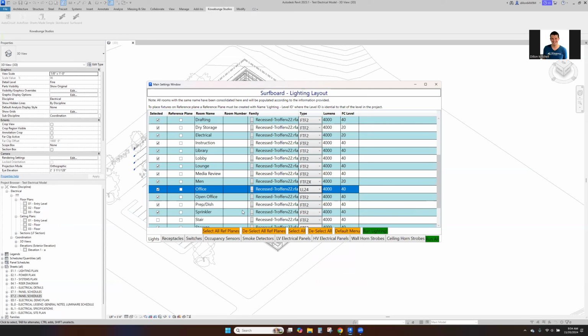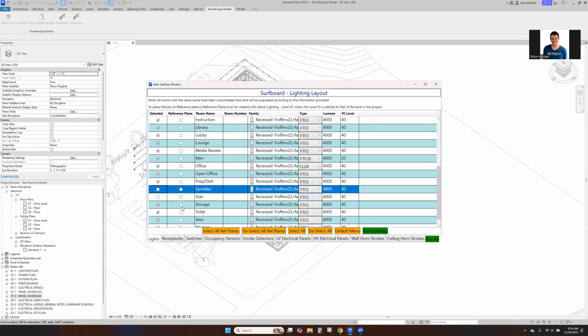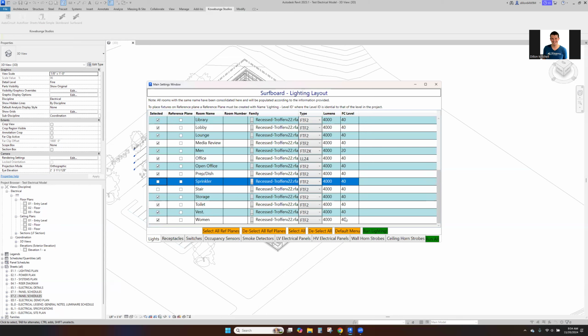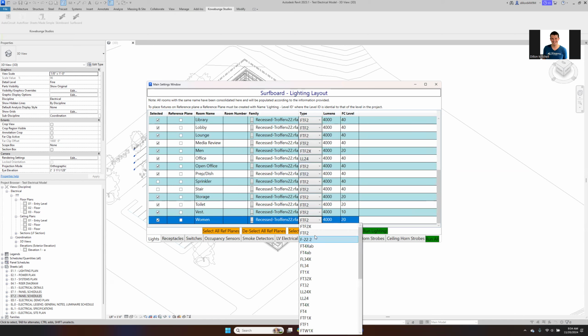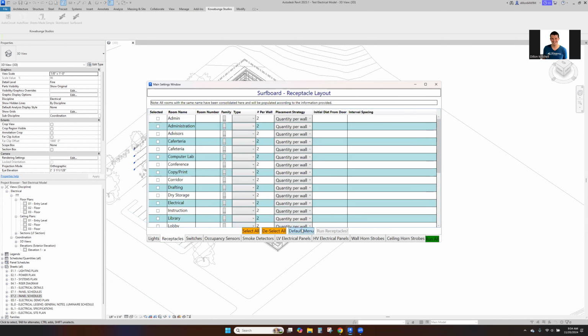So here we go in our vestibule. And again, we're doing basically design as we're going through this and setting these up for success. So again, you're seeing me choose different fixture types, setting different foot candle levels, all from this pretty standard troffer.